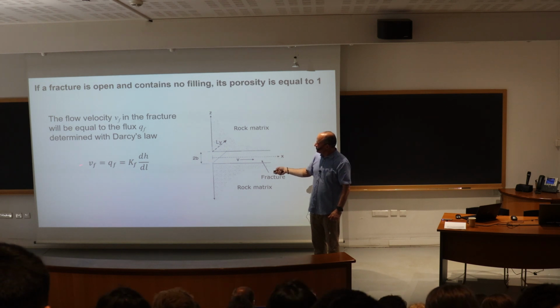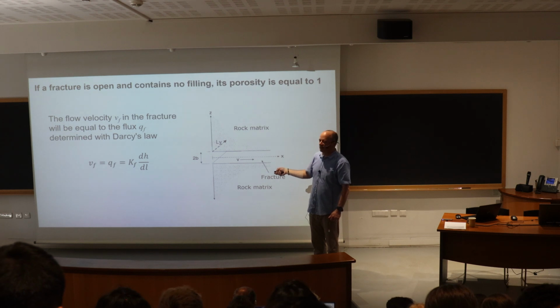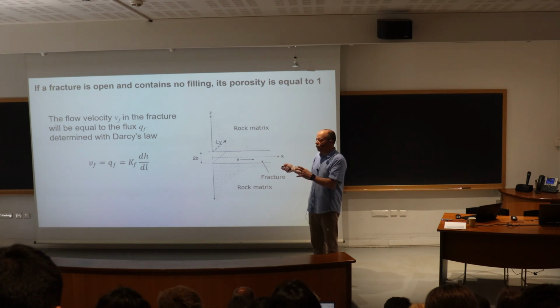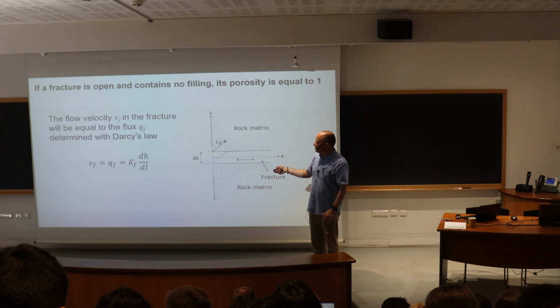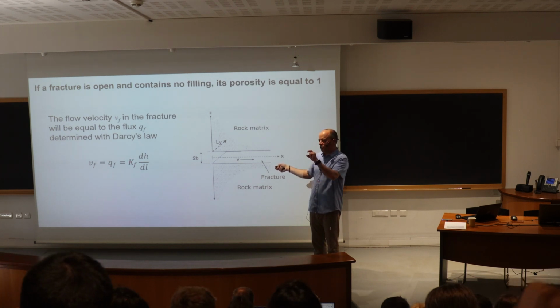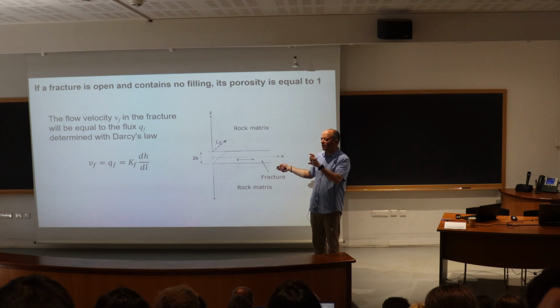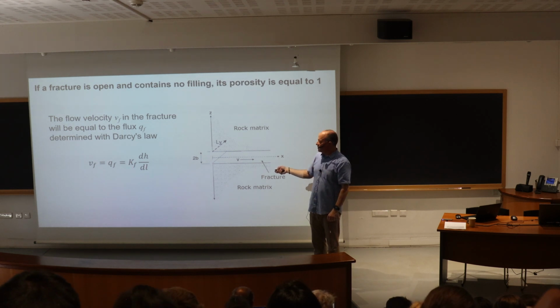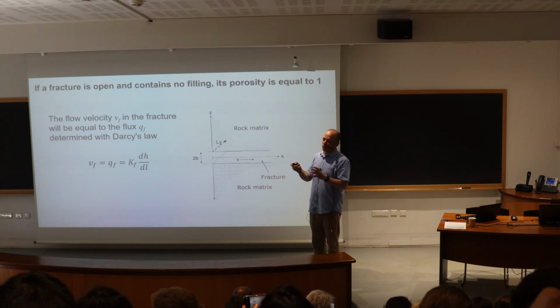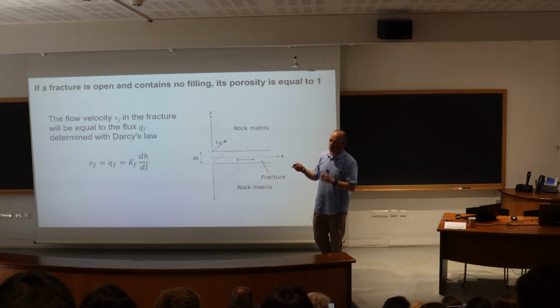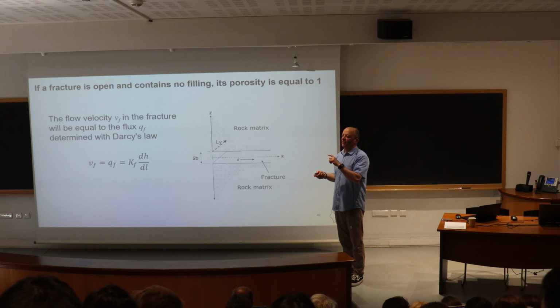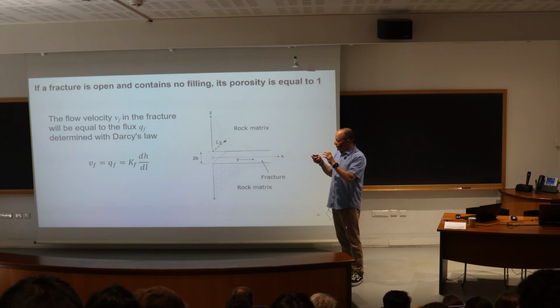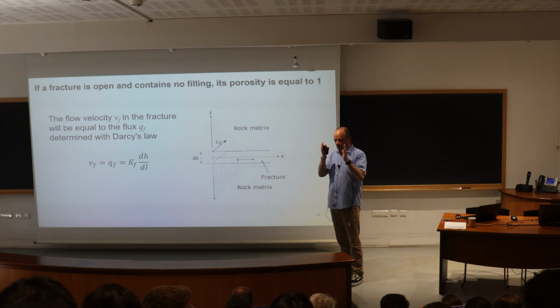from Darcy's law, you multiply by the thickness to get hydraulic conductivity, multiply by the thickness, the aperture, to get transmissivity, and you would get the flow rate. The volumetric flow rate would be the thickness of the fracture, 2b, times Kf times the gradient. And actually, you end up with a 2b cubed, which is the cubic law. So the flow rate is related to the cube of the aperture. For the fracture, the transmissivity is the hydraulic conductivity times the fracture thickness, which is 2b.